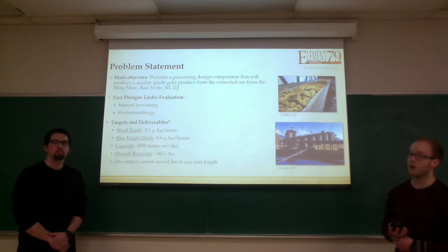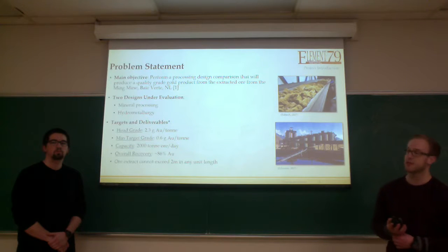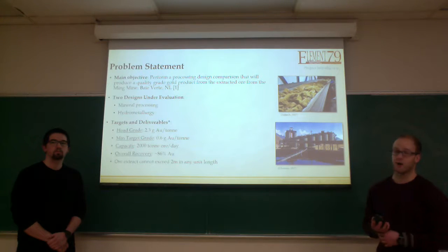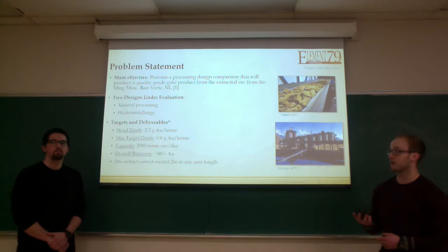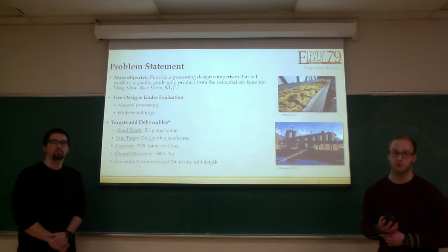So for the problem statement, our main objective is to perform a processing design comparison that will produce a quality grade gold product from the Ming mine in Baie Verte, Newfoundland and Labrador. The two designs under consideration are mineral processing, so flotation, and hydrometallurgy, which is leaching. We have certain targets and deliverables, one being head grade of 2.3 grams gold per ton, a minimum target grade of 0.6 grams of gold per ton, and capacity of 2,000 tons of ore per day.